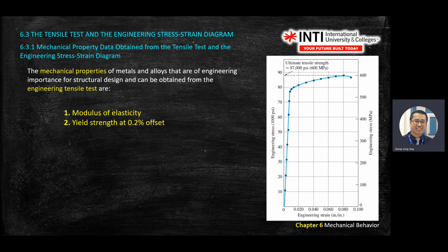So, I already explained about the modulus of elasticity just now. Are you able to get the modulus of elasticity from the experiment data? Anyone still don't know? Let's say you get a perfect graph. I draw something on the whiteboard here. You connect the line, you select all these, or you use the Excel function. You plot until here, then you find y equals mx plus c. You find the Young's modulus from here.